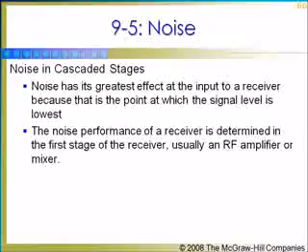So, the design of cascaded circuits must ensure the use of very low noise components, and we should take into consideration the current, the resistance, bandwidth, and gain figures in these circuits. Noise is no longer a problem beyond the first and second stages of the cascaded circuit.